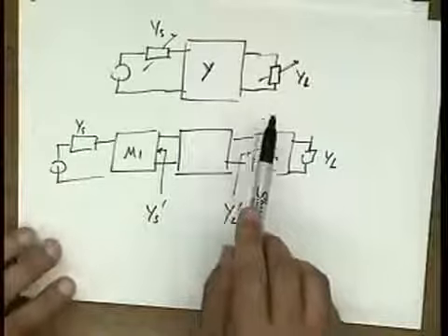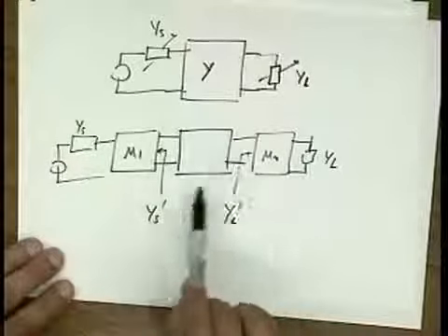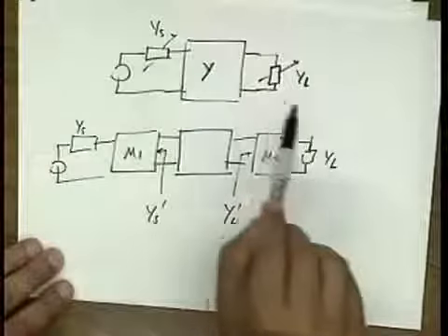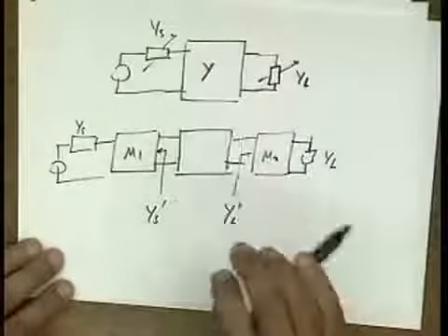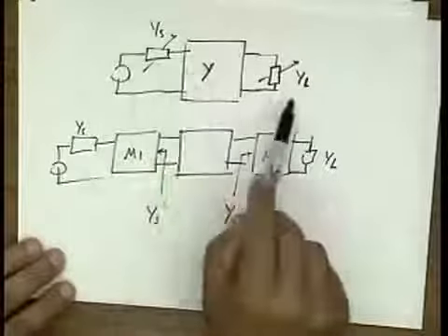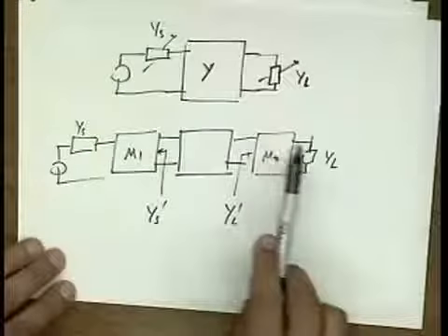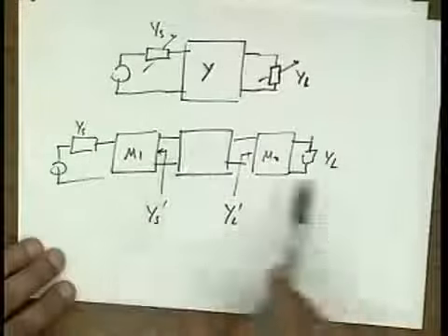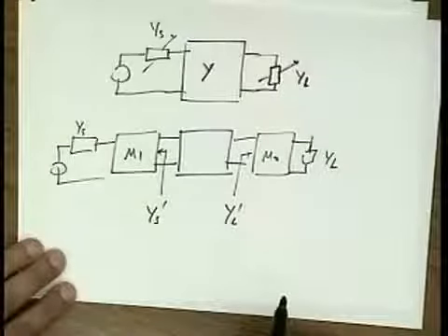So as a circuit designer, once I've picked my transistor, I can pick my source and load admittance optimally in order to get the maximum power gain. Now, if I can find out that there is a certain optimal load and source, then I can synthesize matching networks that convert the real source and the real load impedance into those optimal impedances.